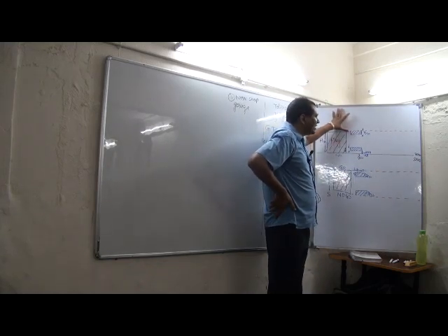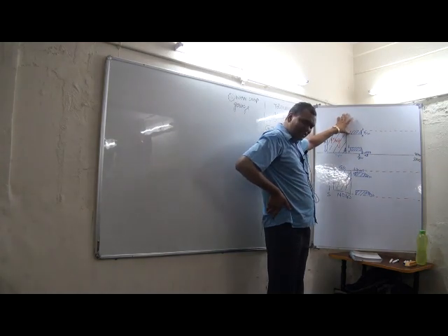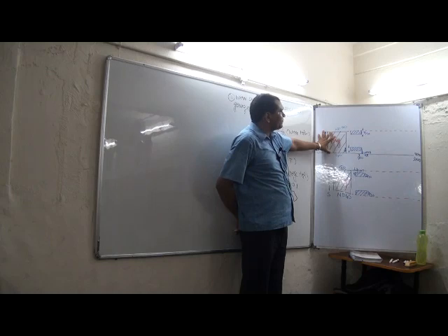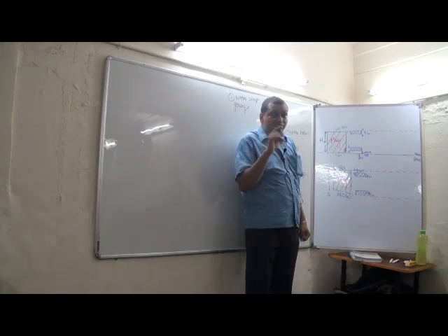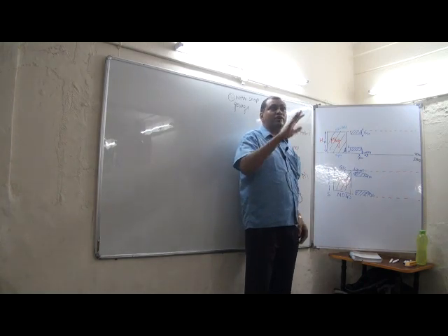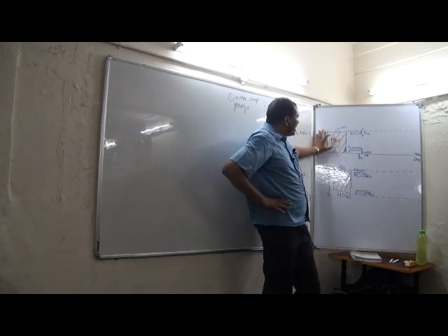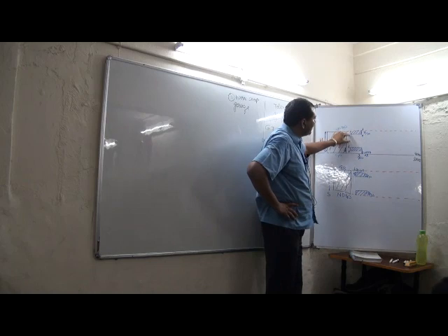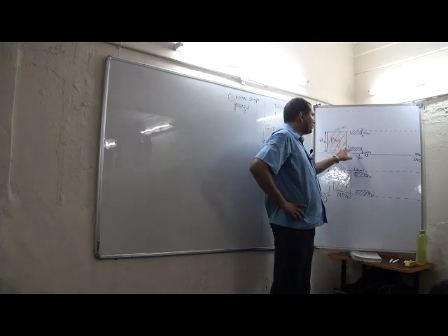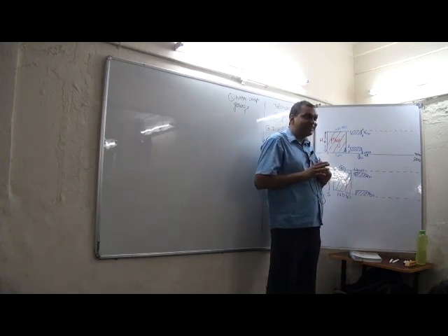And what is the significance of tolerances? Our gauge can be anywhere in this range. That is the meaning. What is the meaning of tolerance of a hole? Our hole may appear anywhere in this range, because tolerance refers to a group, not the individual component. Similarly, to check this type of hole, for our no go gauge, the dimension can be anywhere in this range. This is the minimum dimension and this is the maximum dimension. For the go gauge, this is the minimum dimension, that is the maximum dimension. Is that all right now?